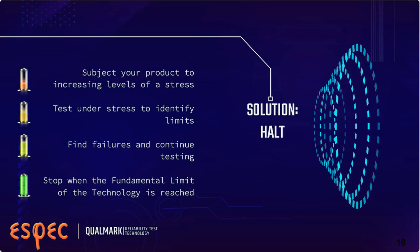Once you find these failures, you figure out a way to get around them or work through them and continue testing until you've learned everything that HALT can show you. And that happens when you hit the fundamental limit of the technology. That's the point where in HALT we say we're just not getting valuable failure modes anymore. We're not learning from the failure modes. We've reached the point where a complete redesign is going to be necessary to get past these failure modes. That's not what HALT is about. It's about finding the easy-to-fix failure modes that will improve the reliability of the design.